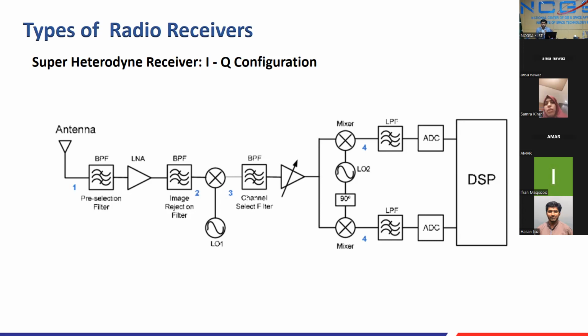because in measurements, when you mix two cosines with a 90-degree phase, you get, at an oscilloscope, you won't see that on a spectrum. On an oscilloscope, you will find one signal in phase and another 90 degrees out of phase. So if you try to sample that on a single SMA port out of the receiver, you would cancel out at some point. Your information will be lost. So to reject the image more effectively, this configuration is also used.